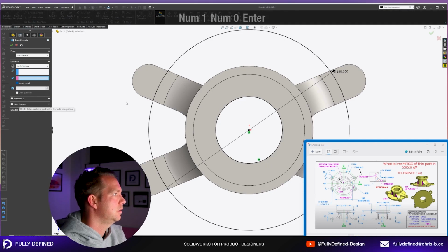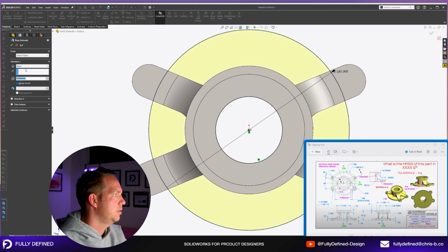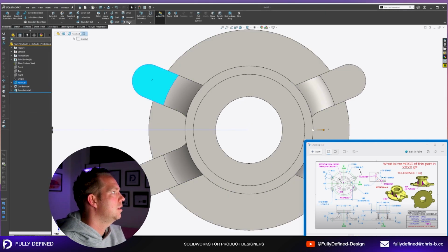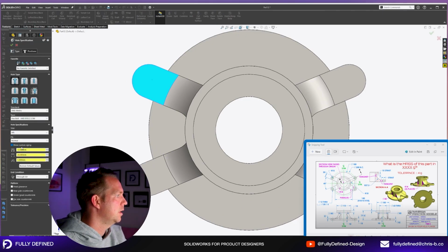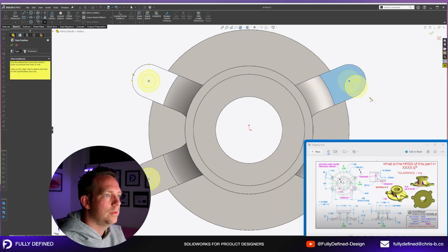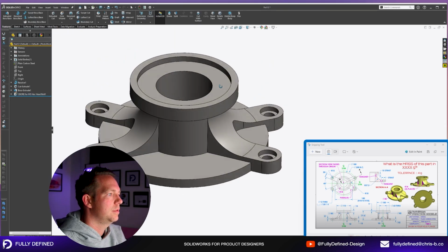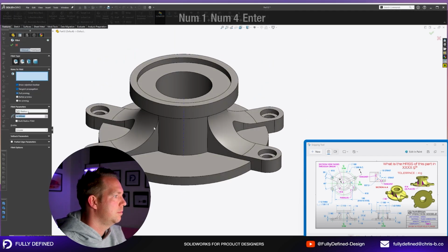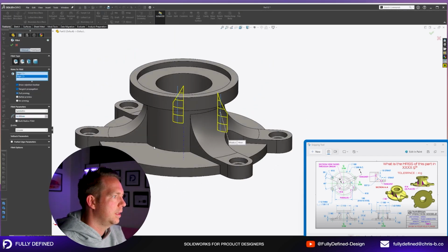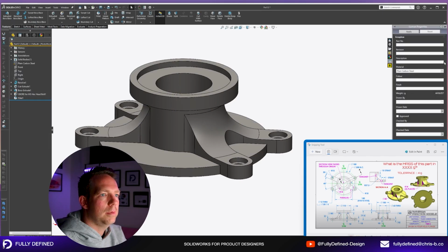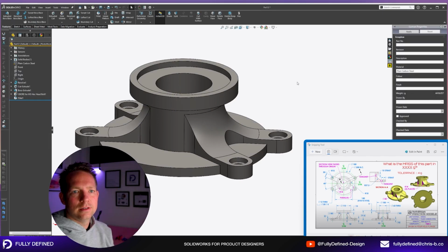This one is a simple extrude up, 10mm. Here we need to do our holes. I've got the settings for the counterbore already in there, 12, 20, and 5, going through all. I just need to find the positions. I'm on center point. And then our last step is going to be those fillets. 14mm, 1, 2, 3, 4. No quick selection for these ones. And then measurement 4416, done.